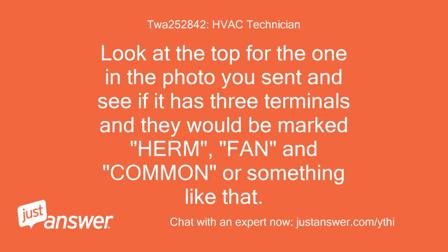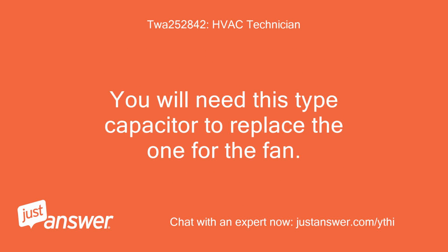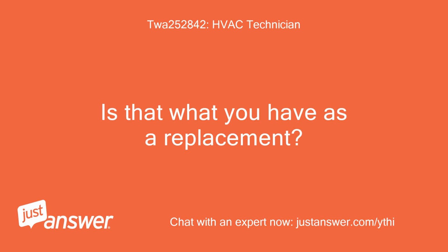Look at the top for the one in the photo you sent and see if it has 3 terminals, and they would be marked HERM, fan and common, or something like that. You will need this type capacitor to replace the one for the fan. Is that what you have as a replacement?